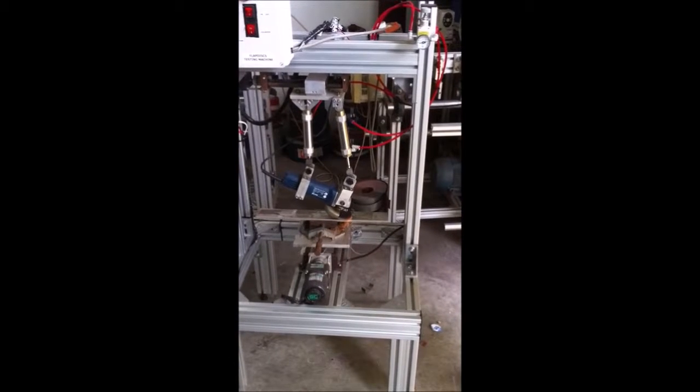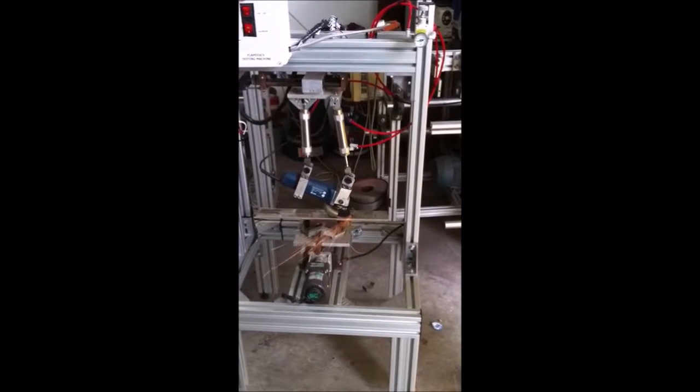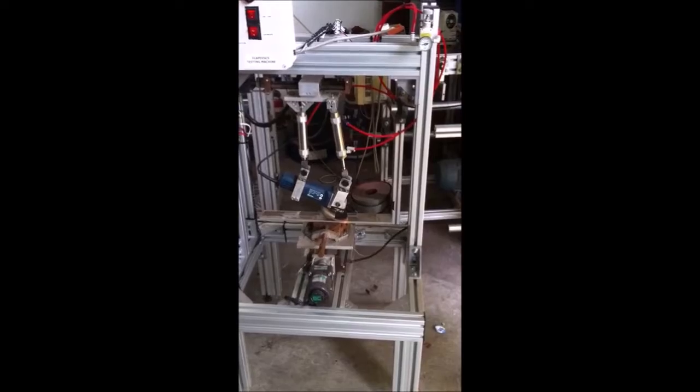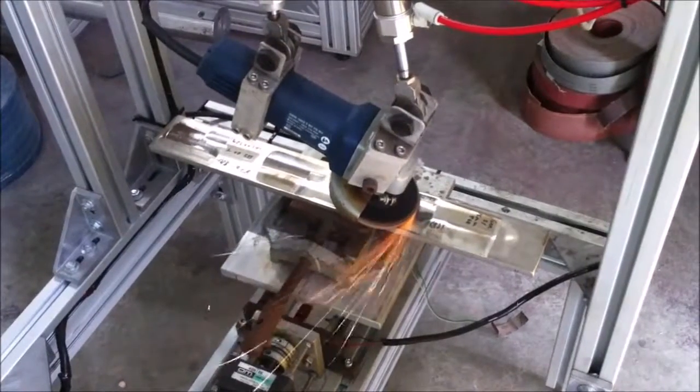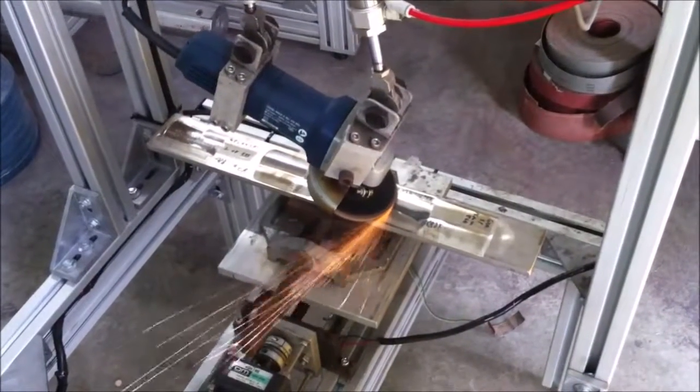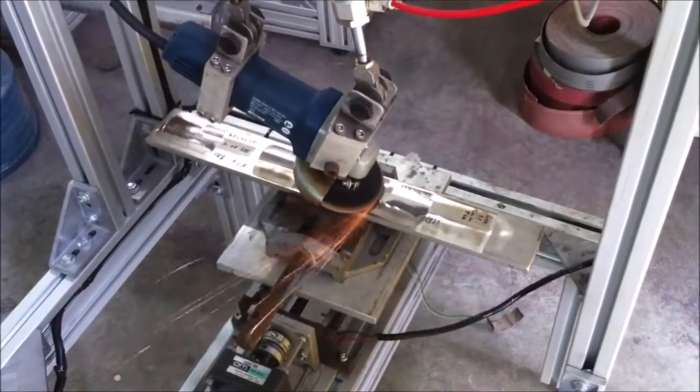The grinding wheel can be operated at different speeds. Higher speeds are usually desired for better surface finish. Lower speeds decrease the grinding temperature, however, this can also be remedied with sufficient lubrication. The rotating speed should not exceed the safety limit since it would cause the wheel to crack and can lead to breakage.